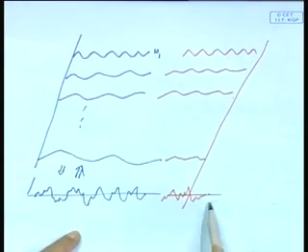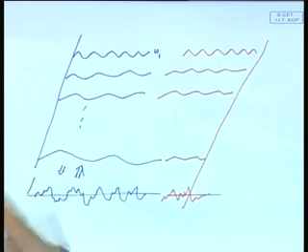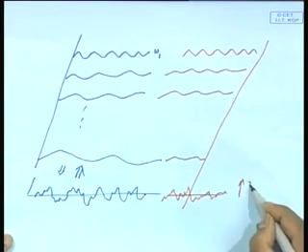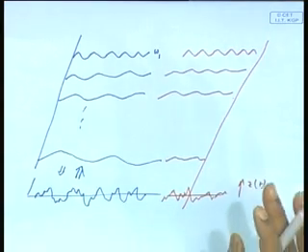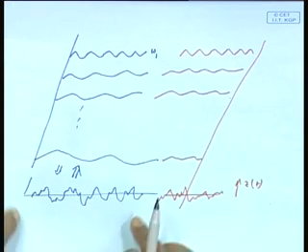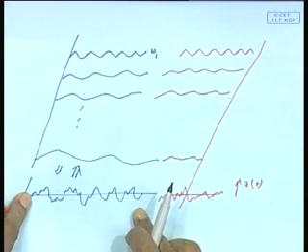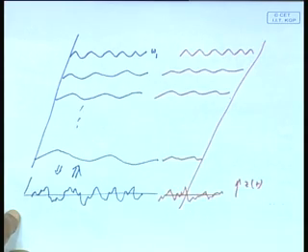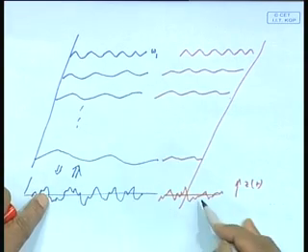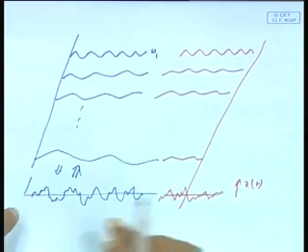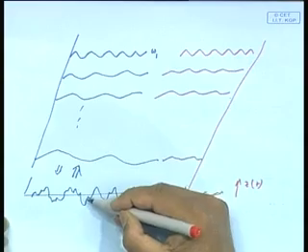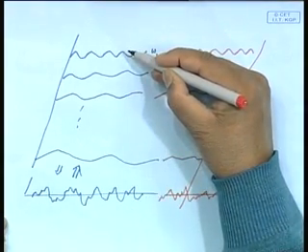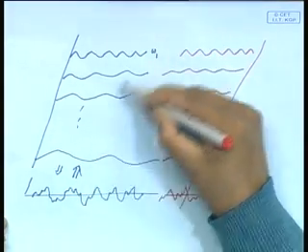See, I have to predict this line, this red line, which is my response output, which is my Z in t. This is actually my Z(t), that is how it is heaving in irregular wave for this eta(t). That is what I have to predict. The question I am asking you is that given this, what is this? Now I have seen that this is nothing but sum of this, which I have done by spectrum. So what I do, I break it down to this sum.